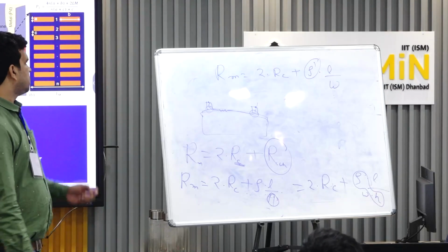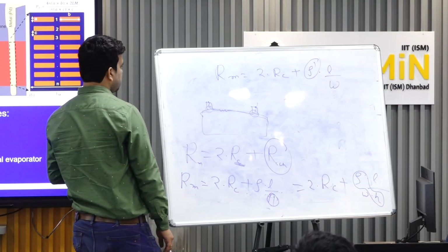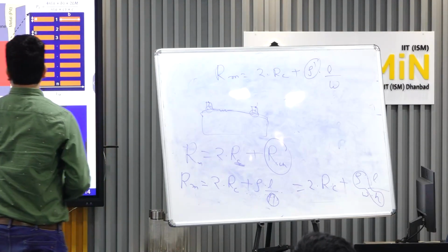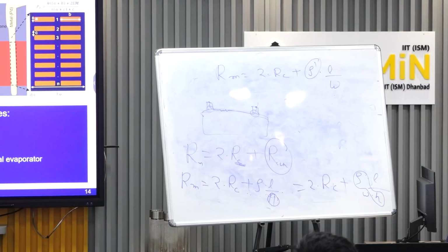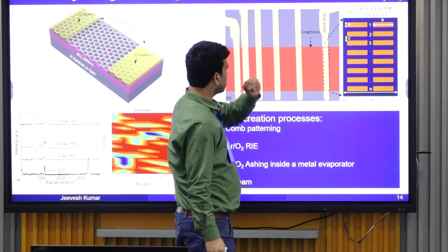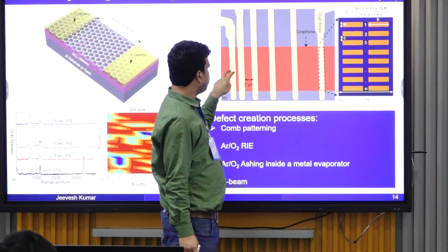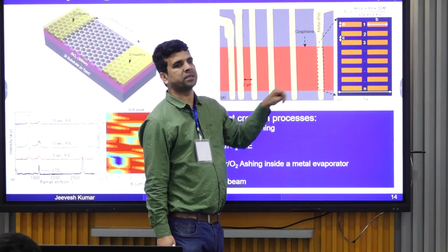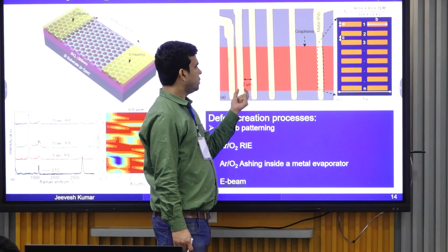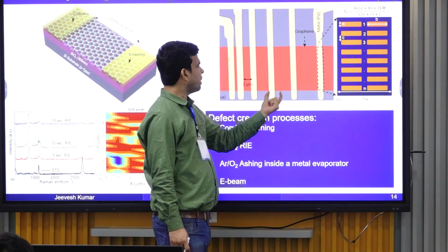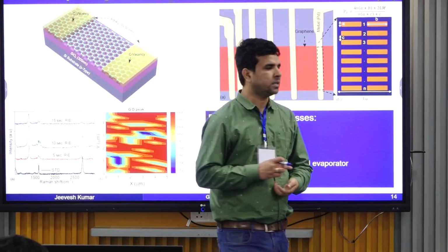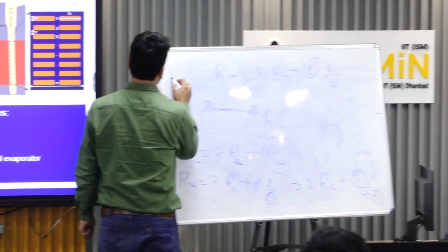Understood? So now, we are creating this type of structure. See here now, how to find out the contact resistance. In the structure we are putting multiple pads, multiple fingers with a variable distance: 1 micrometer, 2 micrometer, 3 micrometer, 4 micrometer, 5 micrometer like that. So we have multiple pads with multiple distances, and then we can prepare a table, right?